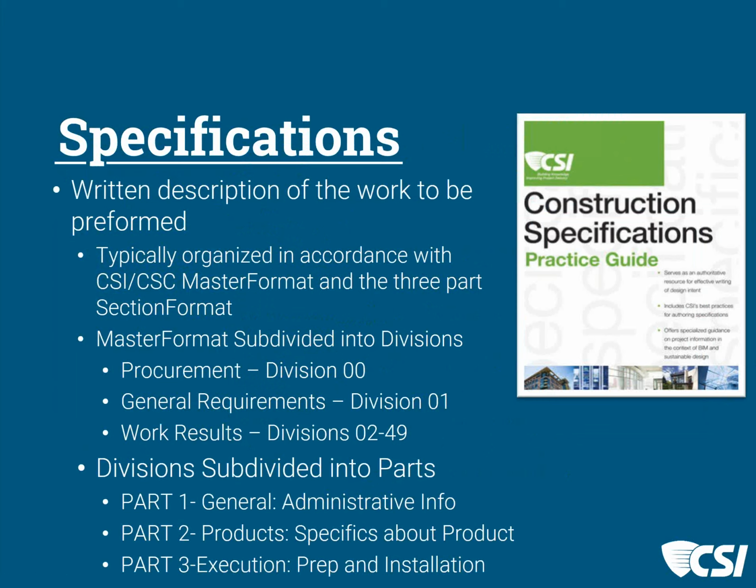So the specifications are another of our contract documents that give a written description of what's supposed to be performed in the field. It's broken down into a very easy, followable format in MasterFormat, divided into procurement processes, then general requirement processes, and then to follow with actually what is going to be put in place out in the field with the work divisions themselves.